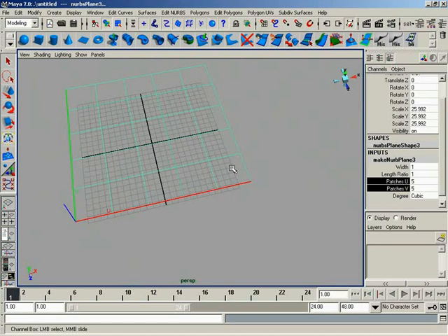If you went through the Maya Fundamentals class, which hopefully you did, you might actually remember running into this yourself. Remember when we did the alien example way back when we did the little flying saucer, we had a little alien who was kind of like an eyeball on a stalk? Attaching the eyelid of that alien, in many cases, not every single case, depending on how you built it, to the body, which was made out of a revolve, caused you to have to reverse your surface direction before an attachment could take place. And I know that was the case when I had to build it, and many of the students who were having problems, it was because they weren't reversing that direction.